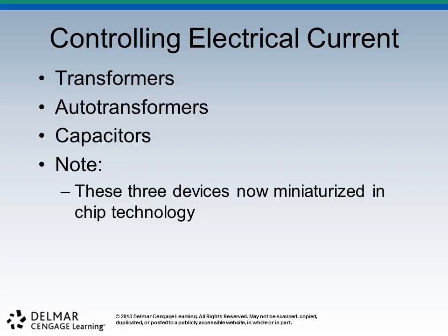Now, I'll say again, I'm probably getting ahead of myself, but at the top of page 79, the one that's marked air core, we've got a short one on the left and a long one on the right. That means that this is what we would know as a step-up transformer. Anytime we go from smaller to bigger, we're increasing voltage or increasing potential. And for example, you will find a transformer that is illustrated much like this one inside our X-ray circuit, what we call the step-up transformer. And that's where the voltage from the wall where your X-ray machine's plugged in becomes kilovoltage, which is going to be used to make photons later on to X-ray your patient.